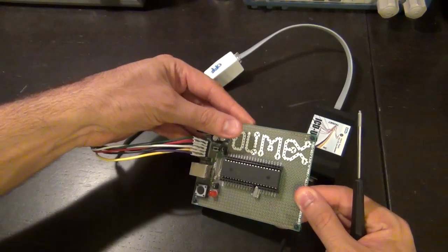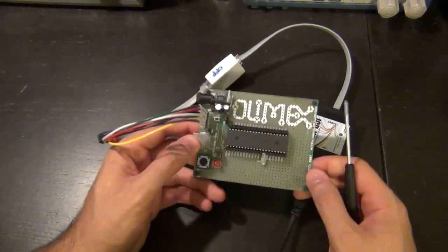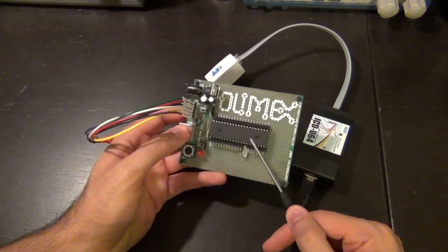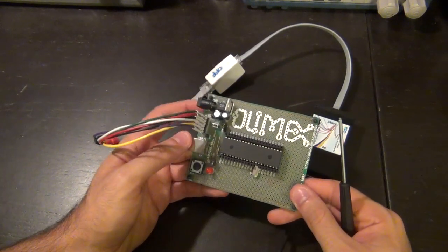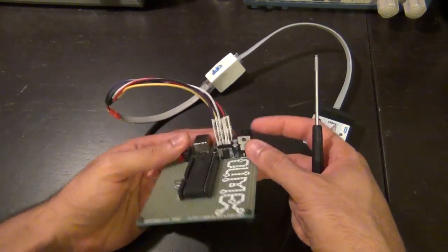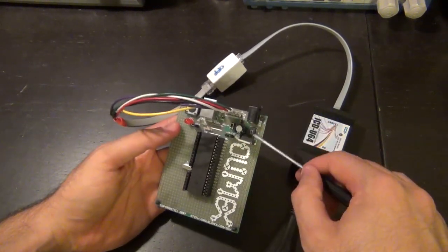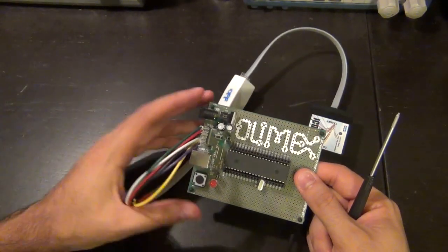There's really nothing else in there except a switch, an LED, and a USB port, because this particular PIC can have a USB connection. But of course you can't program this through the USB. You have to program it with the ICD, the in-circuit debugger interface. So you have this little voltage regulator here and some diode bridge in here to protect it, so even if you reverse the polarity, nothing would happen.